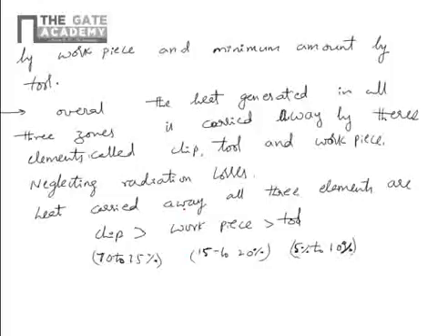So the total amount of heat: overall the chip carries the most heat, next is the workpiece, and next is the tool. Why it has to be like this is because if the tool carries more heat, failure takes place early, because if heat is absorbed more, it goes into deformation.